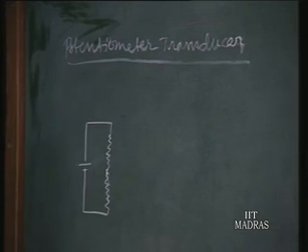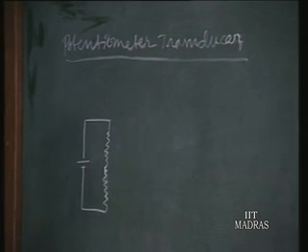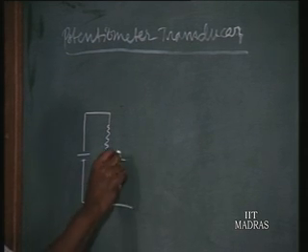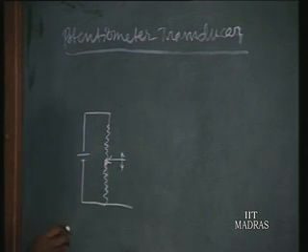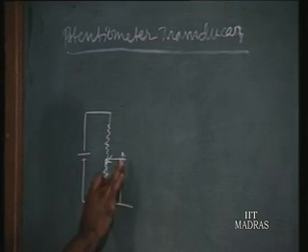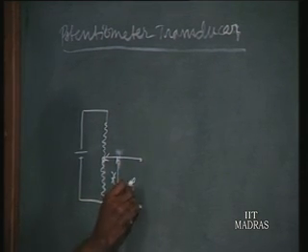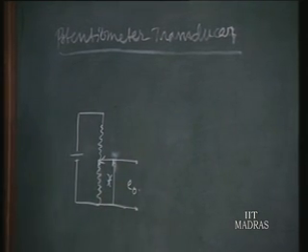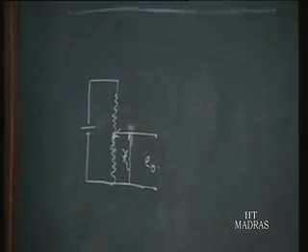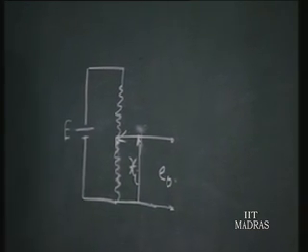Now the second important circuit is the potentiometer transducer, which is often used in mechanical measurements. It is a transducer, that is, it is used to sense or transduce a displacement xi into a corresponding voltage, say EO. This is the output voltage. This is the potentiometer, which has its own excitation voltage.